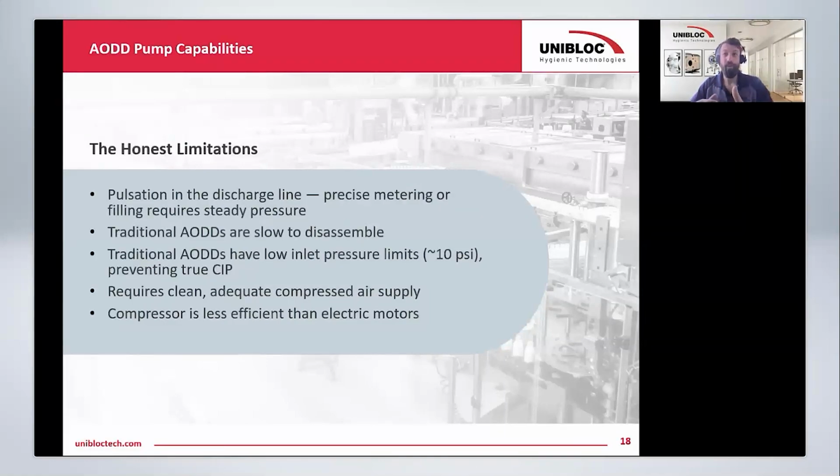And then while we're talking about air compressors, powering a pump with an air compressor, there's a little bit of an efficiency loss because you're going from electric to an air compressor, and that pressurized air is going through a line to your pump. Whereas with a lobe pump, for example, it's an electric motor, gear reducer, or sometimes even just an electric motor directly bolted to the pump. So you have a little bit higher efficiency on those.